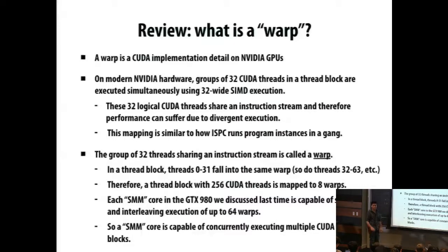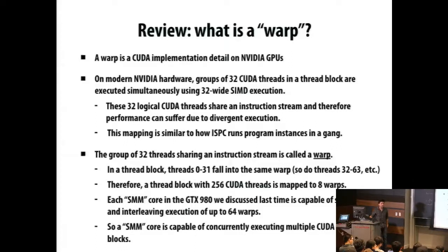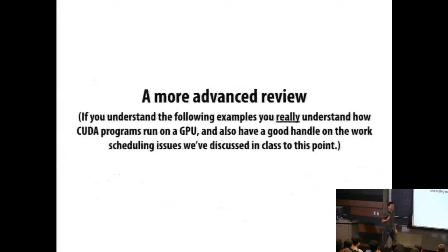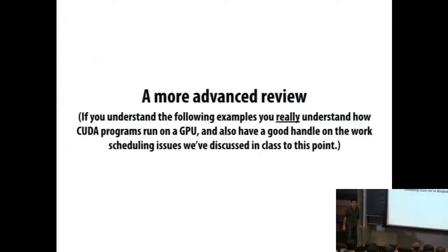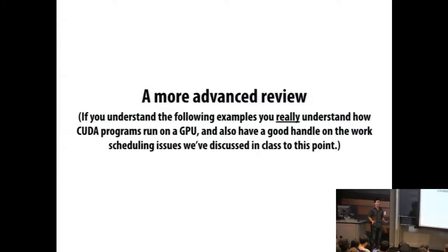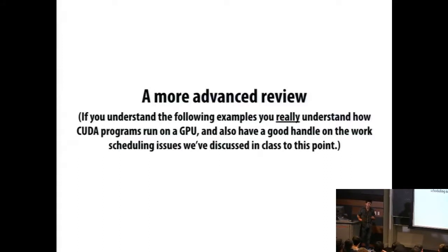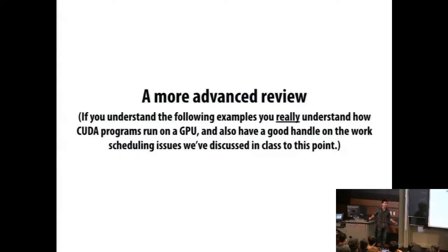Yes? Is warp defined by having 32 threads, or could it be some other number? NVIDIA could change this in their hardware without you having to recompile a binary. Now, of course, they've broken that by giving you instructions that vote across a warp and things like that. So the pretty abstraction has been broken. But yes, for many pieces of code, you would not have to recompile the code to get 64-wide execution or maybe 16-wide execution on a lower end part.